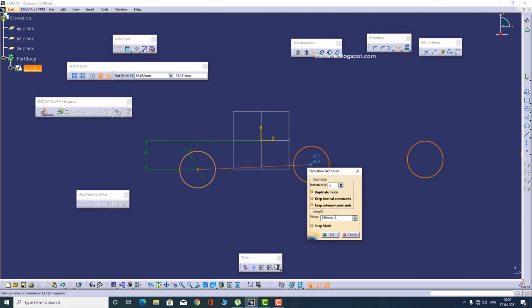If you right click here, you can change the step value, say to steps of 20 mm instead. Now it moves in graduations of 20, 40, 60. You can use this option for translation.